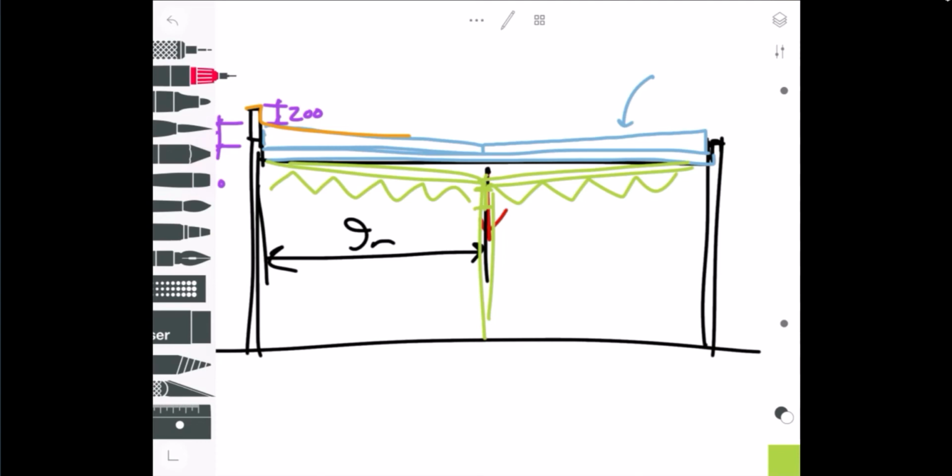Probably, but I suppose it is dummy proof to slope the structure because they could just go in there and do their basic roof with one thickness of insulation, and it wouldn't be a problem. You would still have the slopes. So anyways, those are some considerations for the two approaches that are generally used for getting a slope on the building.